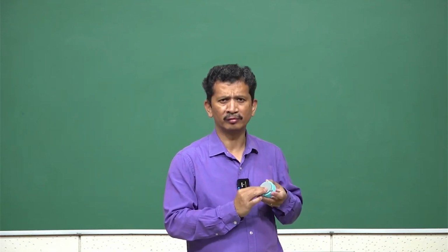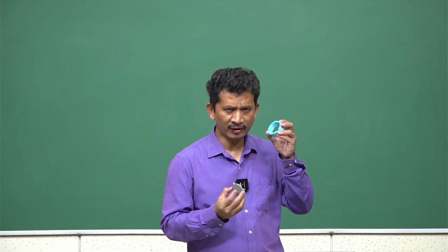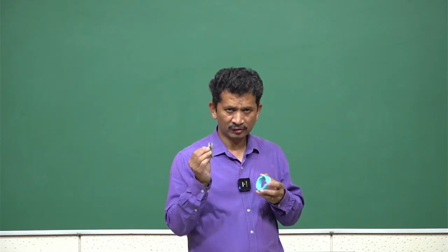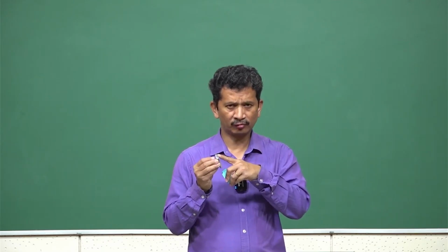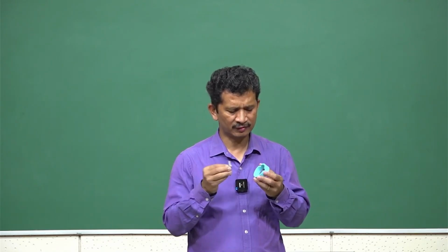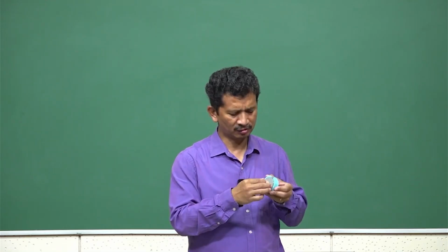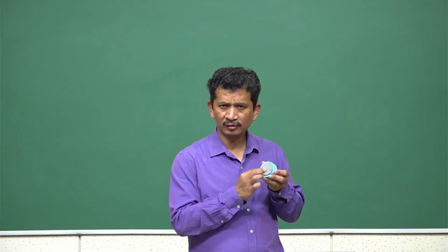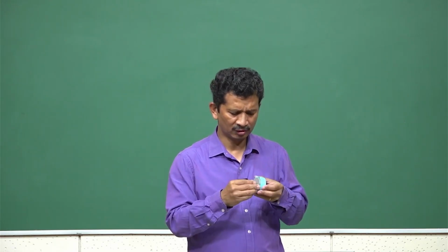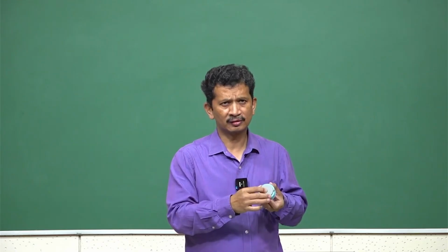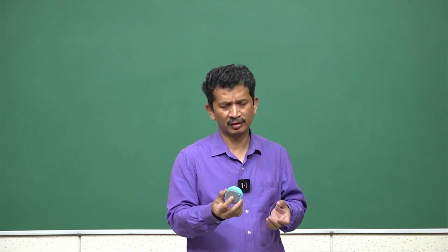it cannot go wrong. So, even a thin tube with this kind of contact, so we can have bar or cylindrical surfaces, and if we just make them touch, if we establish the contact, it will go to the center every time. I can do that. So, again it is an exactly constrained system, six constraints defined.